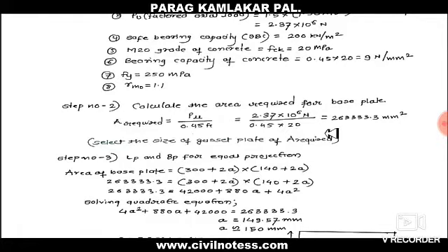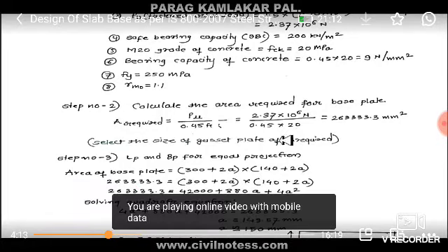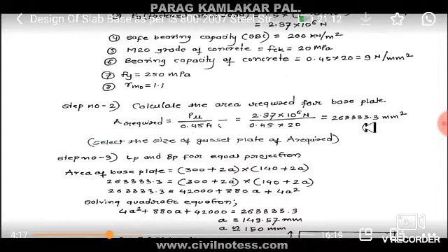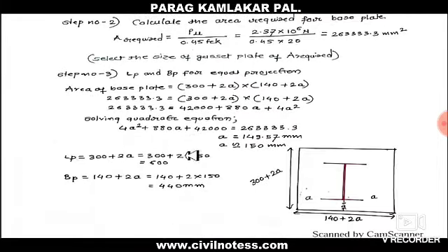What will be the formula? Okay, the formula is area of base plate, which is this one. It's step 3, okay, equals 300 plus 2a into 140 plus 2a. So now what exactly does a mean?